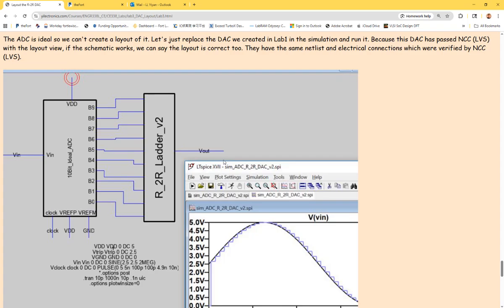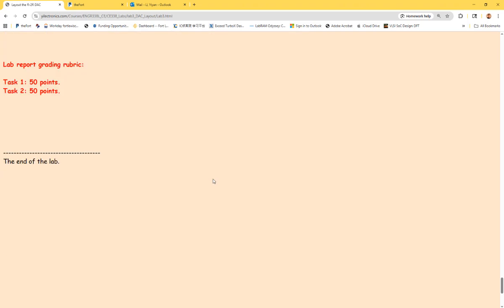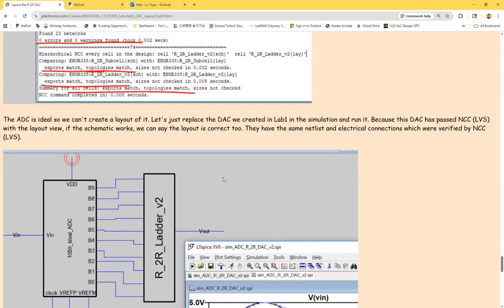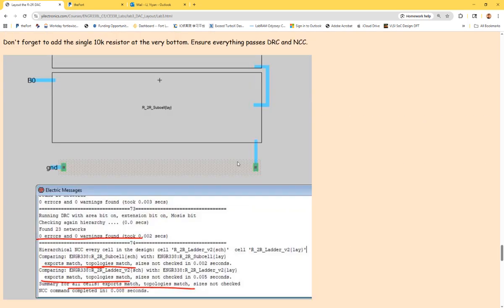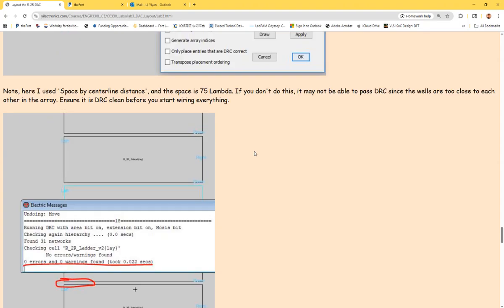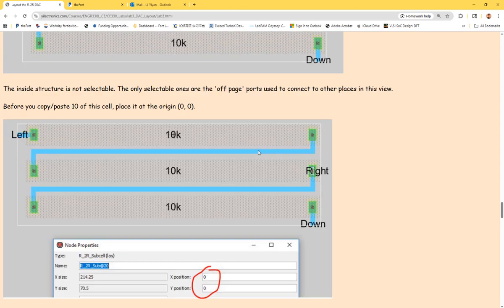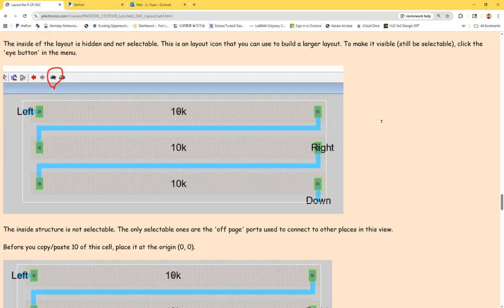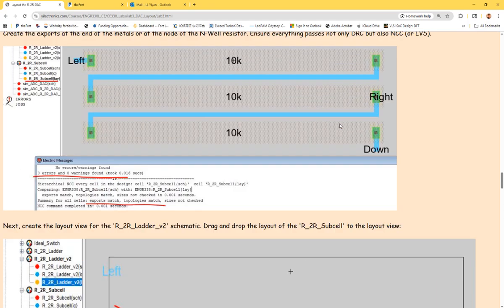So this one is a modular schematic. It's not a layout. So put a modular schematic and connect it with the ADC and do the simulation. If it works, it's a success of the lab. And I think this one is relatively simple. We don't have too many things covered in here, but just letting you guys know about modular design, running DRC and LVS checks, and a sheet resistance calculation, and that's it.